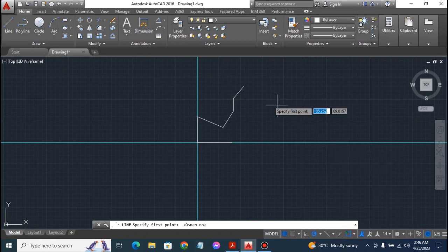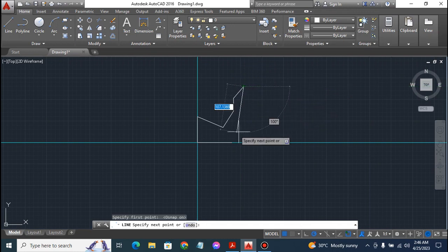All right, turn it back on. All right, so you lock it into the end of this line. You click on it like so. Then ensure that the line is at 90 degrees. You see the way it's locking to the 90 degrees angle. Okay, ensure it's at 90 degrees.